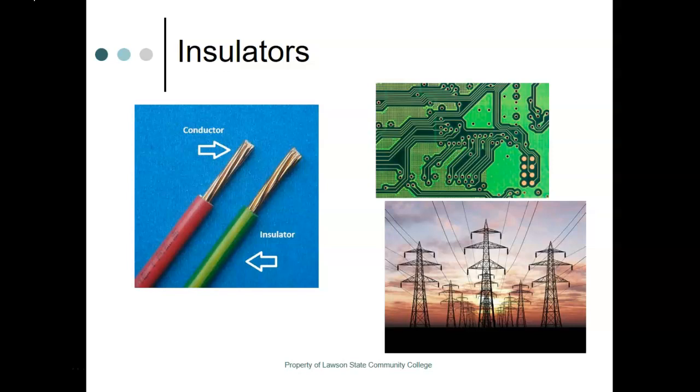So copper is one of those things that we do not use because of those two reasons. It's too heavy, it's too expensive. Is it a better conductor than aluminum? Yes. But it is not so much of a better one that you cannot use aluminum for the same purpose. Especially since aluminum is so much lighter, it's far easier to string than copper. That's another reason why it's used.